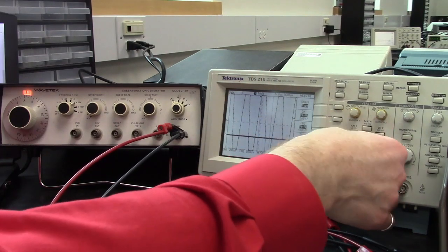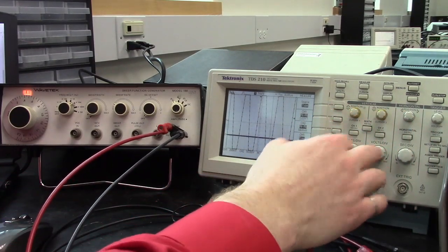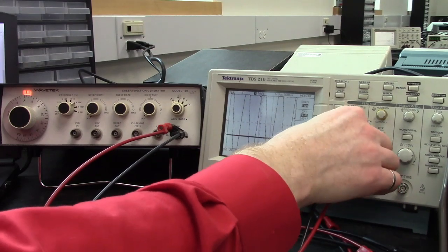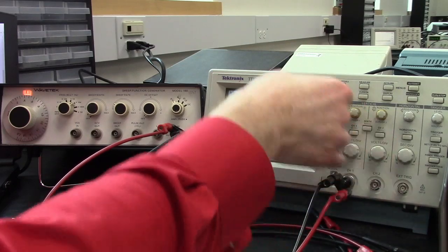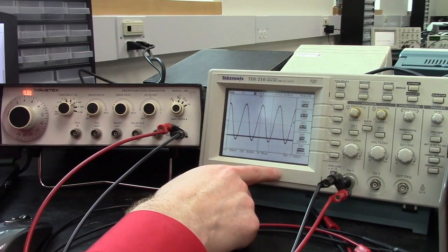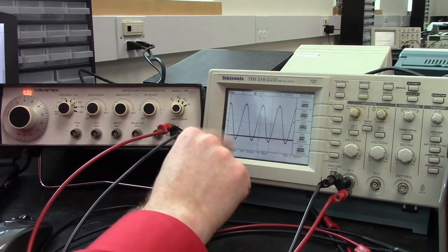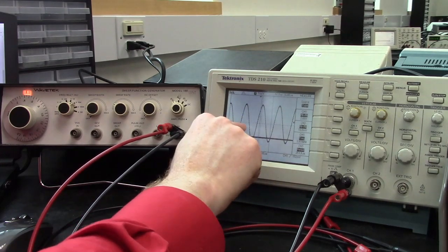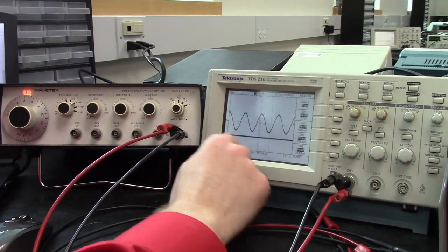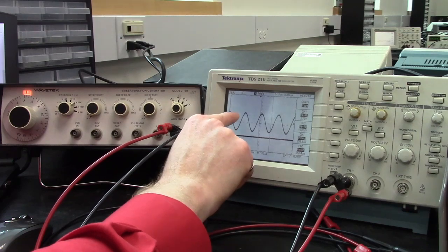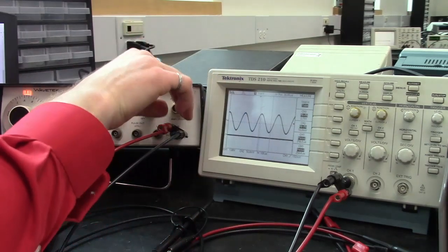So now we need to adjust the volts per division, and that we can do similar to this time adjustment here with this knob here. There's a separate one for each channel. So for channel 1, we're going to use this one, and we're going to turn that to the left to make the signal go smaller, which means that we have more volts per division. So now we're at 500 millivolts per division, and there we'd expect an amplitude of 2 volts to take up 4 divisions. So that would mean 1, 2, 3, it should be about right at the top. If we go one more, then now we're at 1 volt per division. That means it'll take up 2 divisions when we get to a 4 volt peak to peak or 2 volt amplitude. So let's increase that a little bit more.